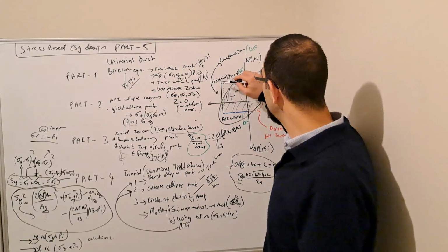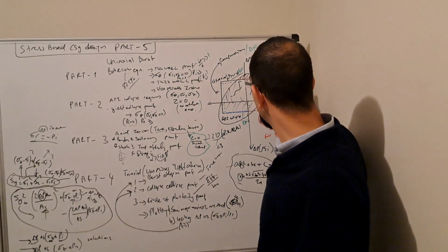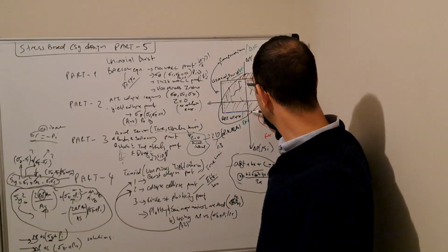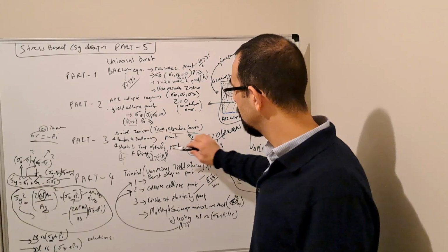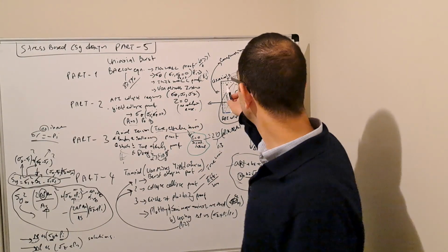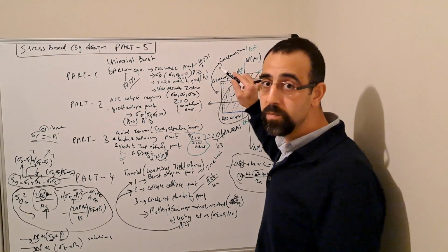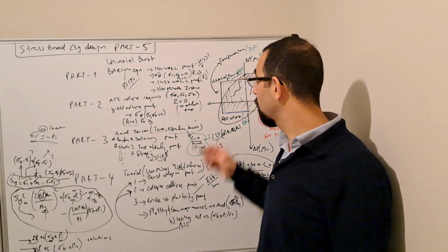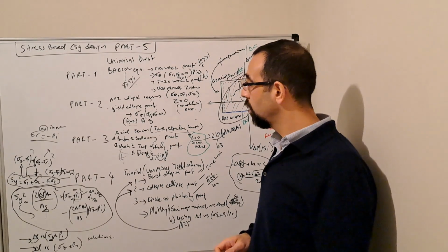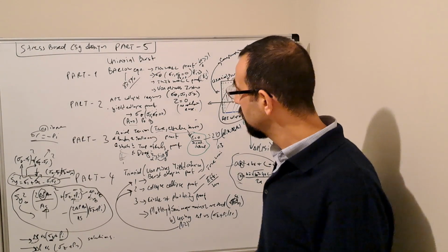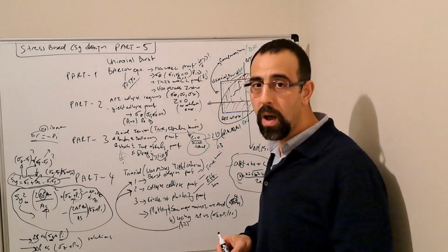On part number 3, we covered uniaxial compression and uniaxial tension, which combine to this line. And then we talked about the different changes, and also, if you remember, there might be some performance difference between the casing and the connection, other than just the design factor, on some kind of low clearance pipe.